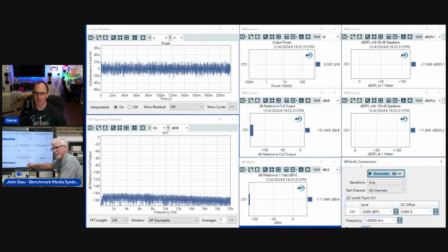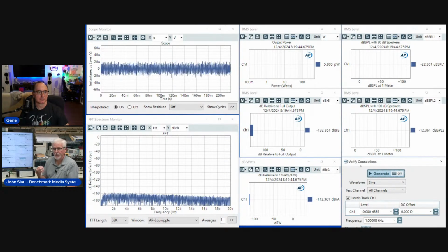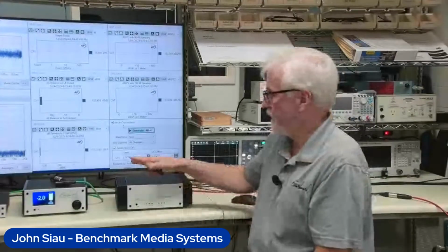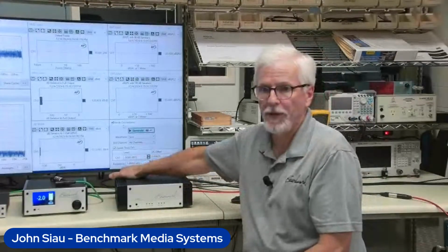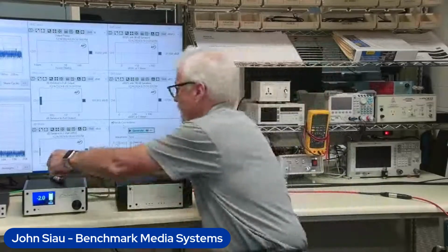Now, it's important to note that when you set it to the low gain setting, you have to have a preamp that has the appropriate voltage output. Most consumer audio single-ended outputs are 2 volts RMS. Sometimes you get up to about 4 volts clean on some consumer audio. And that's what our mid-gain setting is for. Our mid-gain setting is specifically for the 4-volt equipment. So you put the amplifier in mid-gain position, and it's designed to work with a 4-volt signal.